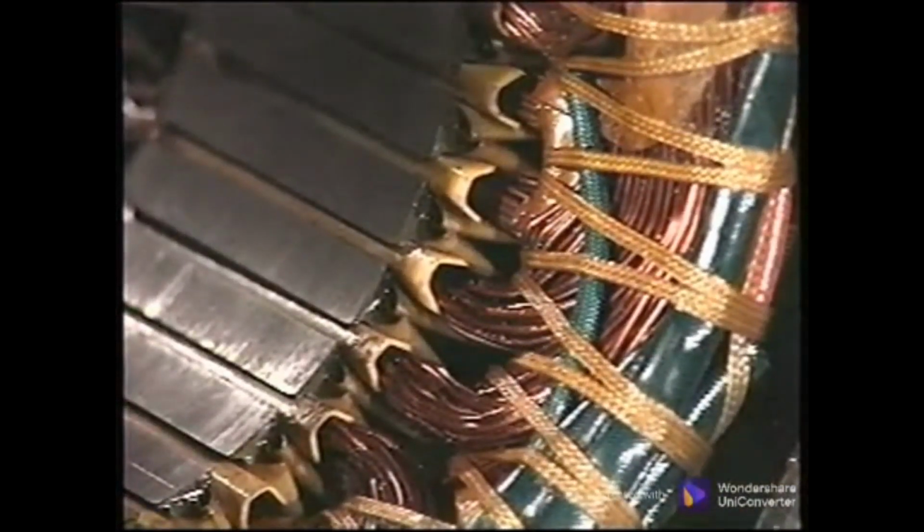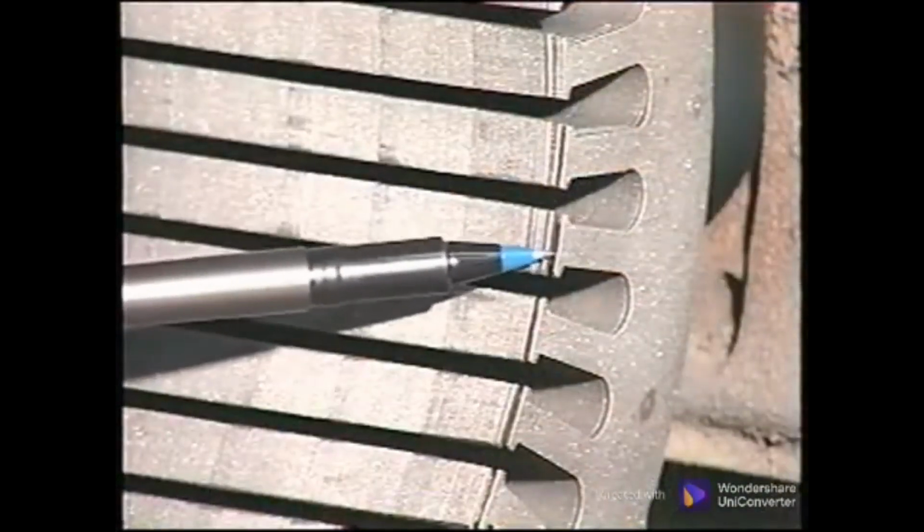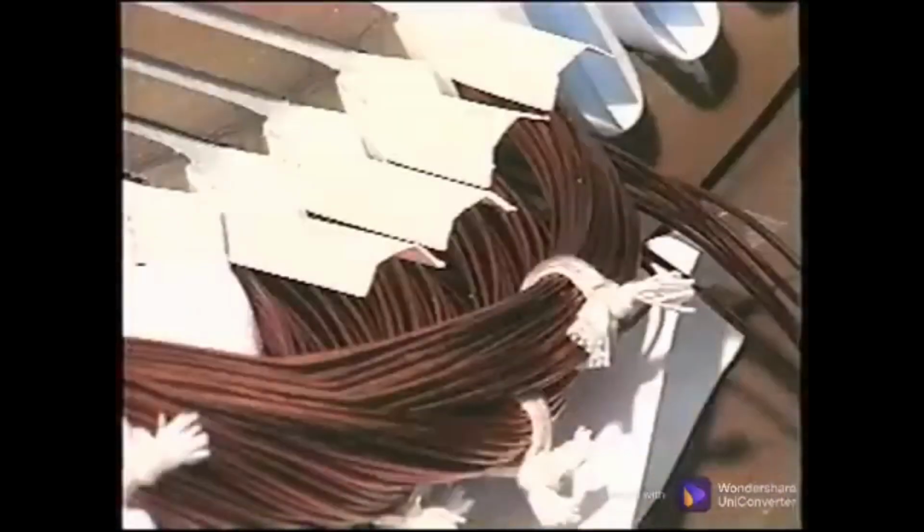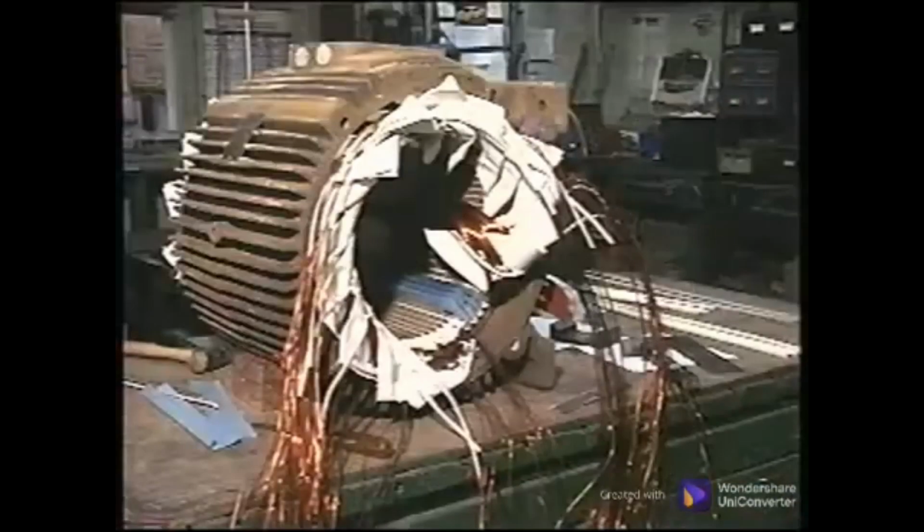The stator assembly is still somewhat flexible though, because it is made of thin soft iron laminations as the core, soft copper wire, paper, and varnish. It is assumed that during operation the stator does not move. However, this footage of a stator during startup was captured with a special camera that allows us to see any action in slow motion. Notice the flexing that occurs. This movement is at a frequency equal to 2 times line frequency.